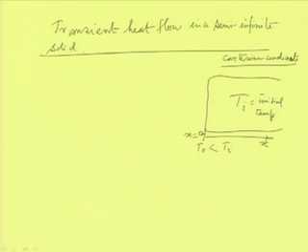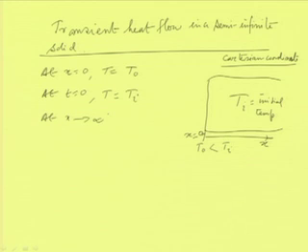Okay. So, according to this, my initial and boundary conditions would be like this. At x equal to 0, this is the boundary condition, the surface is suddenly exposed to To. So, T equals To. And at t equals 0, that is the initial condition, the whole body had been at a temperature of Ti. It happens that at x tends to infinity, the body will have almost the same temperature as Ti. So, T will be equal to Ti. So, this is the condition.